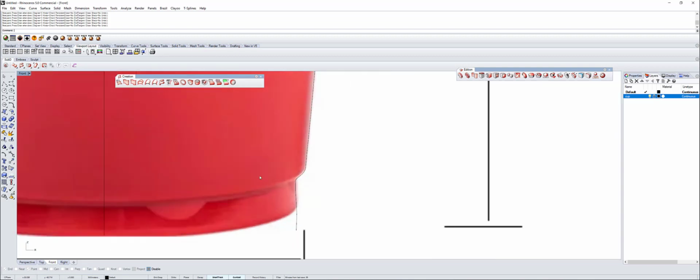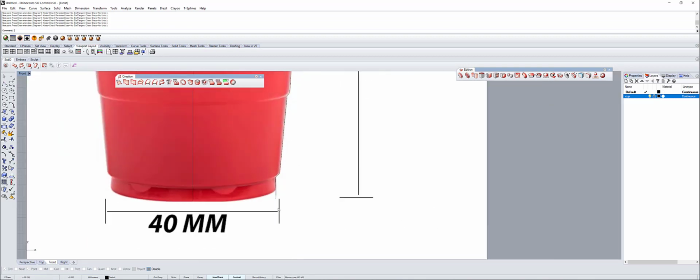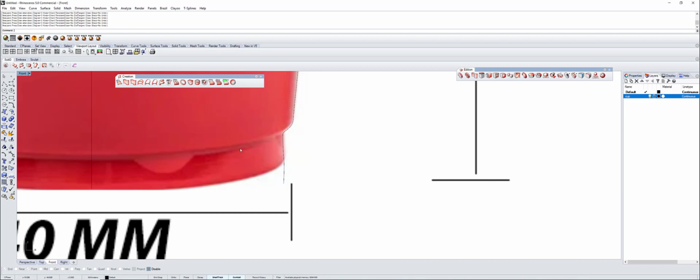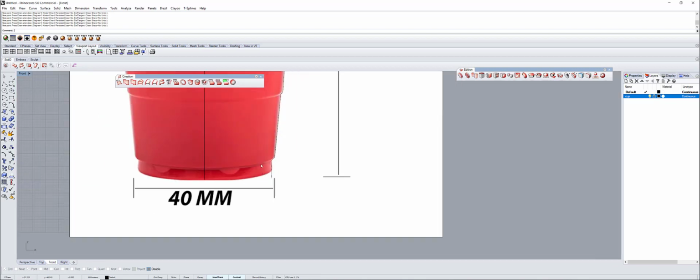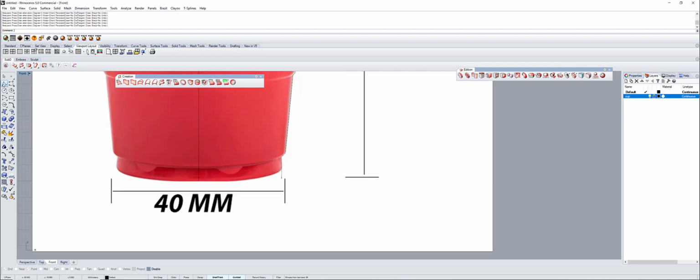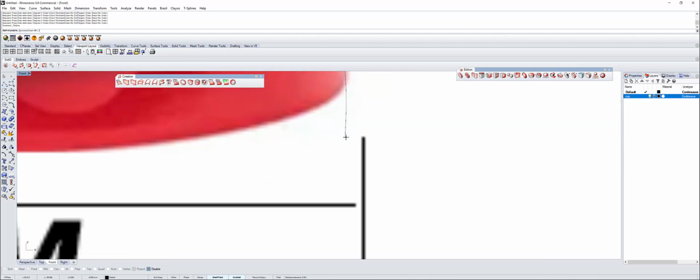So what I'm going to do is, you see those cups in the back, they have a shape where they go along a border, then they go up, then they go to the center. I'm going to do it with this tool, the Polyline. What the Polyline does is that I can draw different lines, and they're going to go straight, and they're going to finish when I press enter.